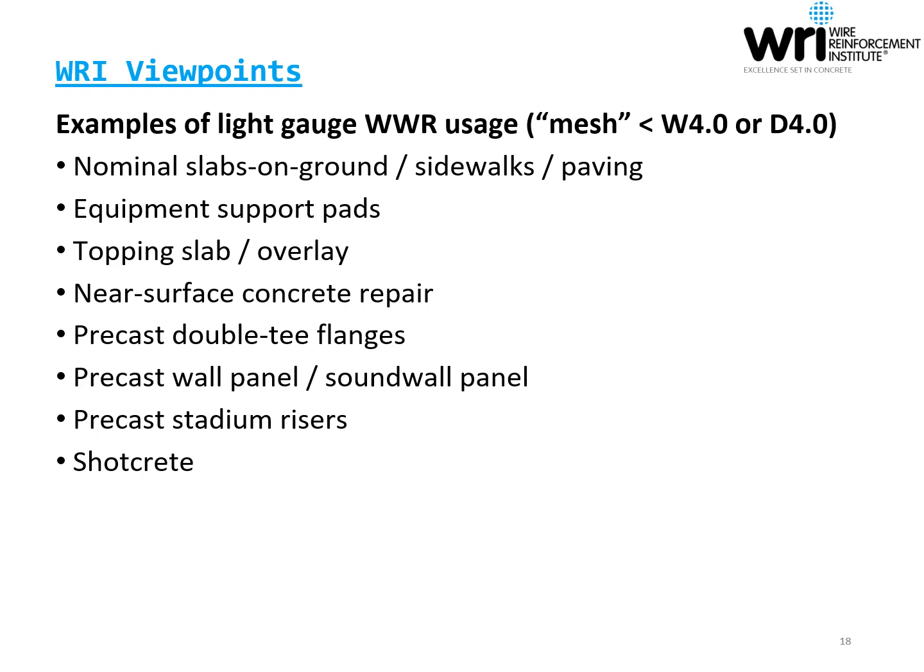Small diameter welded wire reinforcement, also known as light gauge mesh, is characterized by sheets with wire sizes that are smaller than a W4 or D4, and it tends to occupy its own unique category, so it's appropriate to focus a spotlight on this material for a couple of slides. Small diameter welded wire reinforcement is used in a wide variety of applications, some of which are listed here.